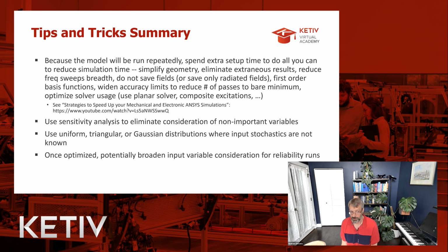And then optimize your solver usage. So you could use the planar solver, or you could do composite excitations, or a number of other tips and tricks there. Please see the strategies to speed up your mechanical and electronics ANSYS simulations, which goes over a bunch of those different topics.